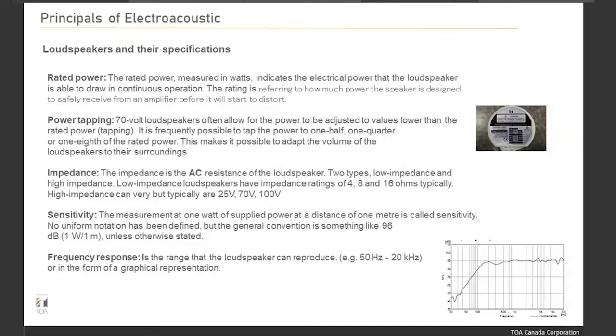If we're using 25 volt at a high impedance, that's usually because we're doing half duplex communication in a school or something like that. So the speaker can be utilized as a microphone to talk back to a master station.